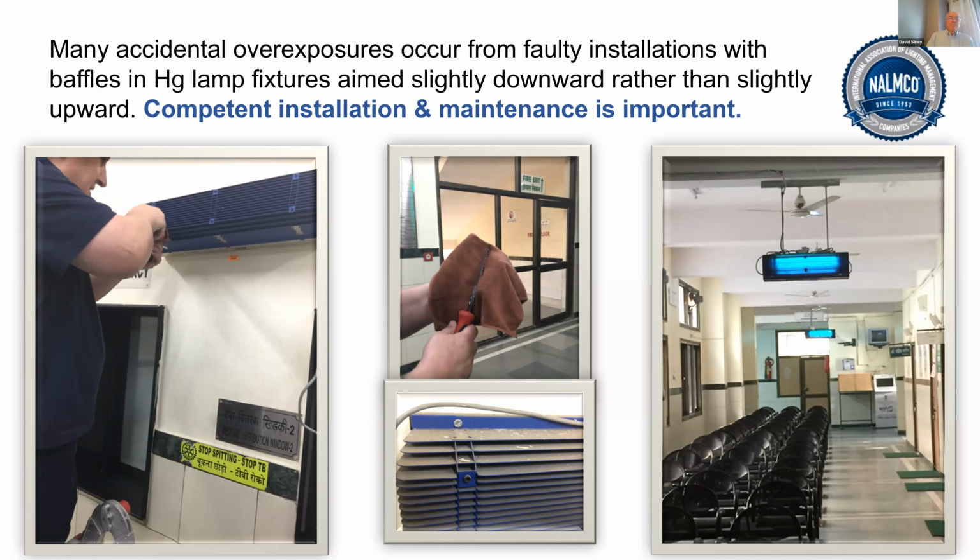So I want to emphasize that most accidental overexposures to UVC, germicidal UV, occur from faulty installations, with baffles and mercury lamp fixtures aimed slightly downward rather than slightly upward. So competent installation and maintenance is important. We say an expert installing UV fixtures. That's a louvered fixture which has a baffle so that the UV from the mercury lamp inside is directed upward, and the individual knows to install it properly.